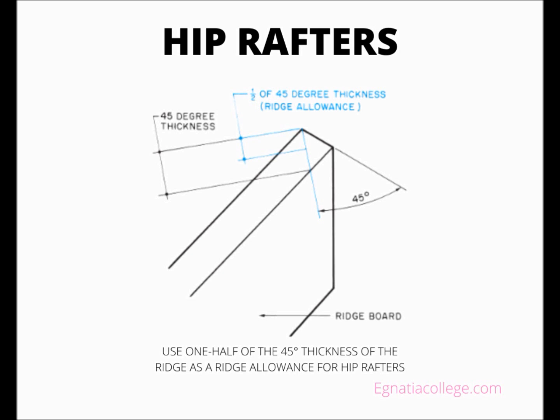Step 1. Find the unit rise, the number of inches of rise per foot of run, at the top of the table. These numbers are the regular graduations on the square. Step 2. Under this number, find the length of the hip rafter per foot of run of the common rafters. Step 3. Multiply the length of the hip rafter per foot of common rafter run, the number found in Step 2, by the number of feet of run of the common rafters, 1/2 the width of the building.